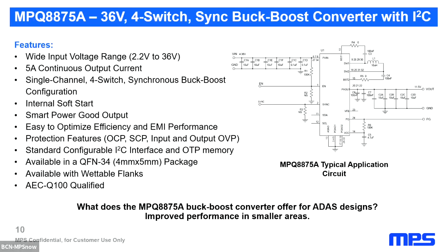Apart from the kind of topology to be used in ADAS designs, it's also important to select the best IC to cover all the requirements. It has been said that the power demand with high output voltages is a must. Then, the proposal made in this webinar is to use the MPQ8875A. This 4-switch synchronous buck boost converter, thought to be used in sensor fusion systems or camera monitor systems, is able